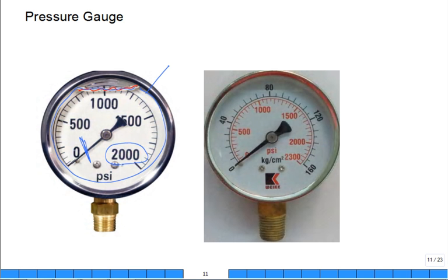2,000. Just like that gauge that I'm passing around, some probably muscle man grabbed it and said, let's see if I can spin it around 3 times. Well, guess what? That gauge is worthless. It was worthless before I used it as a demo. But do not put 4,000 or 6,000 onto this gauge. The gauge is going to be kaput. Something's going to bend or break in there, okay? All right. So that's one thing about these gauges. Respect their pressure range.